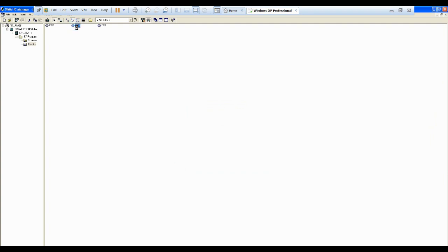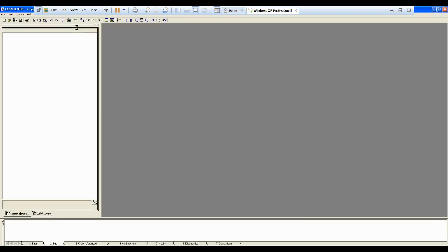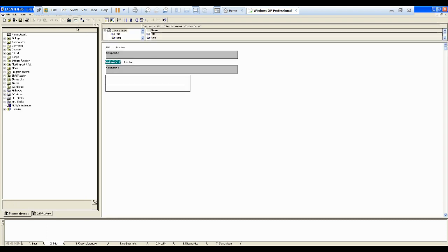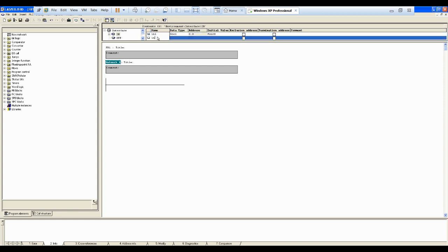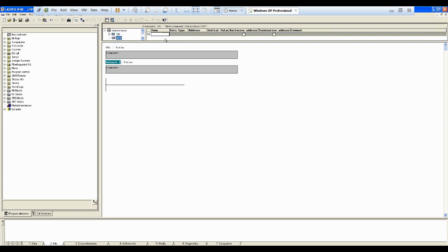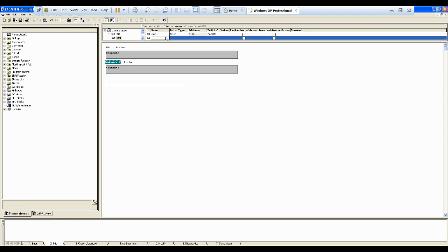Now you have FB1 already here. So the next step is going to be to define inputs and outputs as we have defined in FC. Same way out here we have to define inputs and outputs. So in1, in2, okay, and out, only out, you have to define here, and we are making this FB for power operation, and here we go.